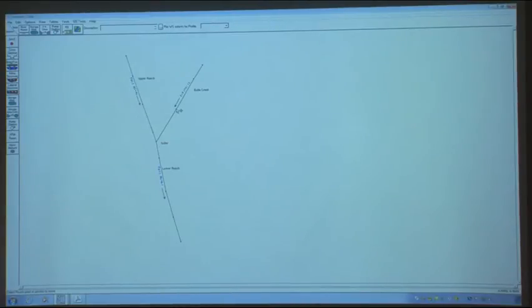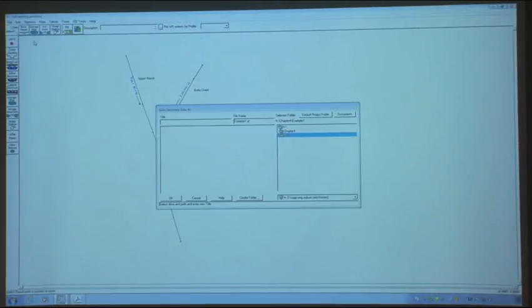You can click on any point, but those are not crucial, because this is a schematic. As long as you set this Y-shaped river network, it will be fine. Edit, move object. Before continuing, let's go to File and save the geometry data.